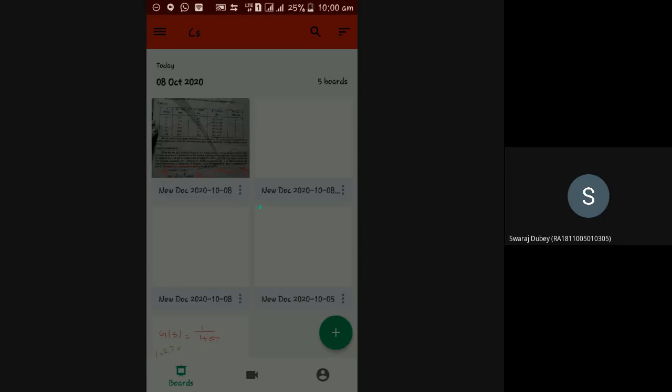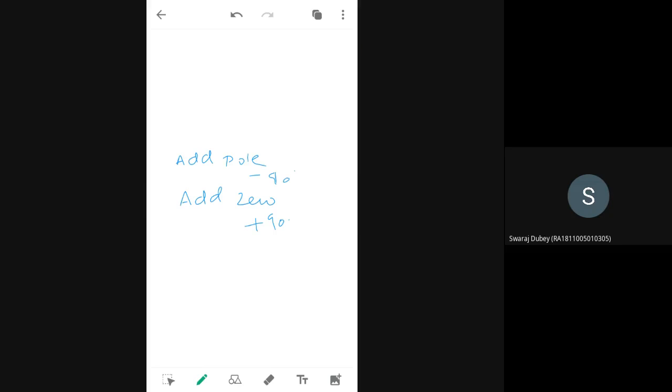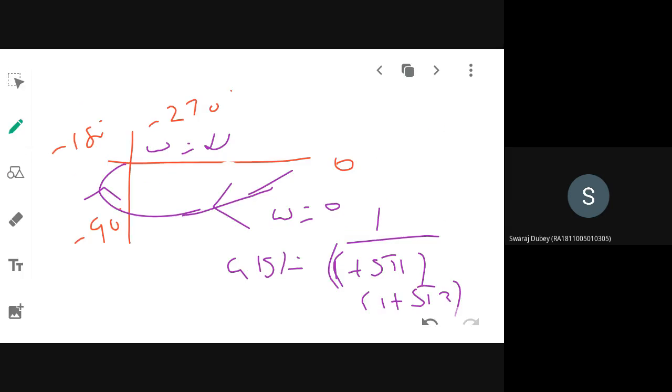So now you have understood what a polar graph is, isn't it? What is a polar graph, once more for one final time? The circles represent the magnitude and the radial lines represent the phase angles. If we have to go in the clockwise direction, we take negative angles. If we go anti-clockwise, we take positive angles. Now, one more thing: where the plot is going to start and where the plot is going to end, that you need to know.